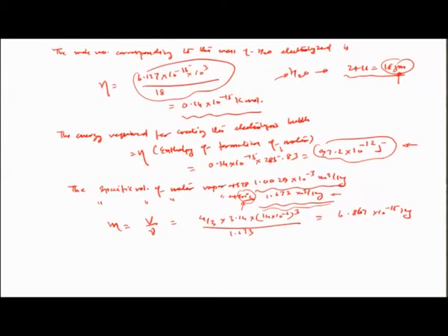So, this is somewhat different from the other value, 6.127 times 10 to the power of minus 15, and that is because the mechanism of bubble formation is completely different. So, you can say that in the gaseous state, the energy storage is a little bit higher than in the electrochemical case, and because of such a difference, there will definitely be a difference in the overall efficiency when we consider the expansion process and the bubble formation process. So, with this kind of a mass of the thermal bubble, okay, let us ignore all the other heat losses and compute the energy required for making such a thermal bubble.